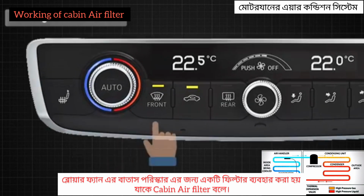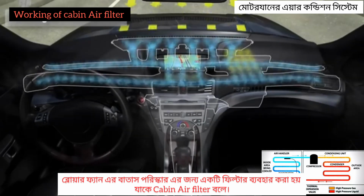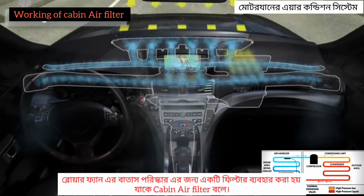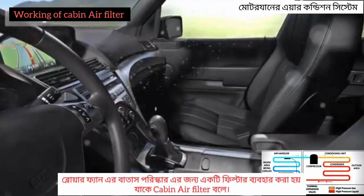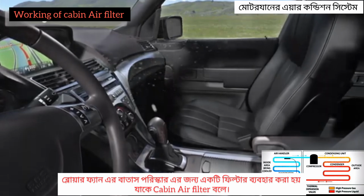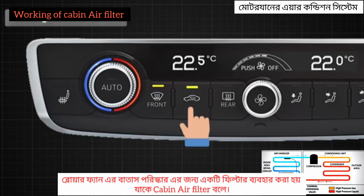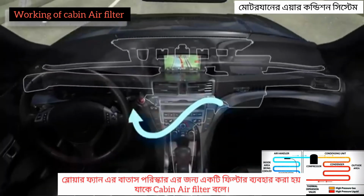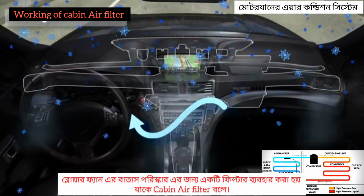Here's how it works. When the recycle button is off, the system draws fresh air from outside. This helps to ventilate the cabin and reduce stuffiness. Fresh air can also help clear foggy windows more effectively, especially in humid conditions. When the recycle button is activated, the car's HVAC system stops the flow of air from outside and recirculates the air already inside the cabin. By recirculating the already cooled air, the AC system can cool the cabin more quickly and efficiently.